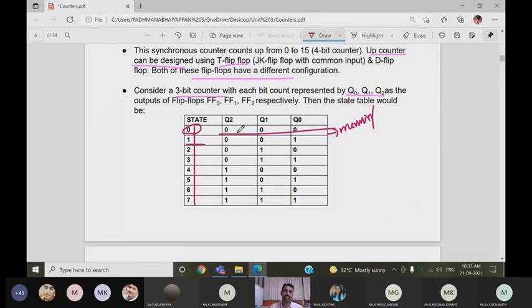So automatically we got that Q0, Q1, Q2 is 0, 0, 0. Okay, so we have to set that clock pulse 1. So it started with 0, 0, 1. Okay, the Q0 is 1, and remaining Q1 and Q2 is 0. Okay, so these values, the same values are repeated, but it comes in the descending order. So that's a down counter, synchronous counter.